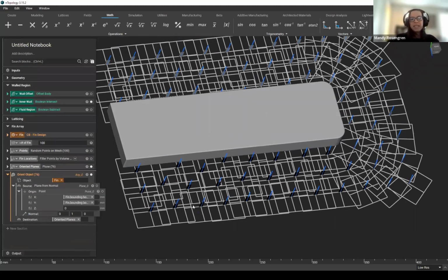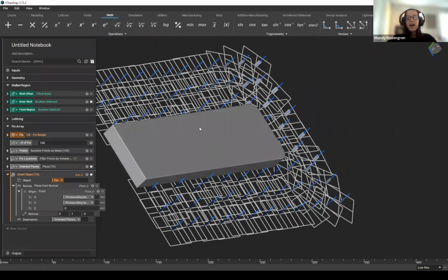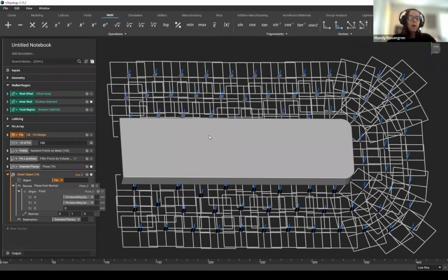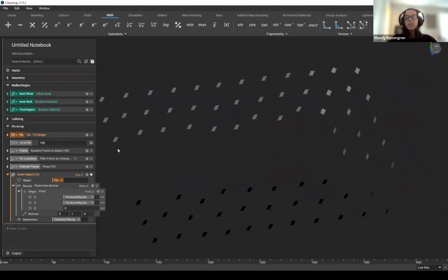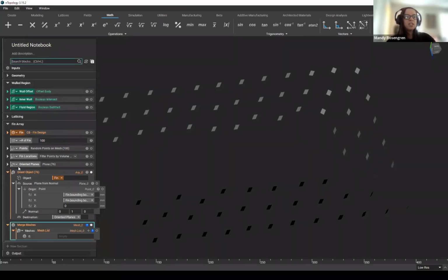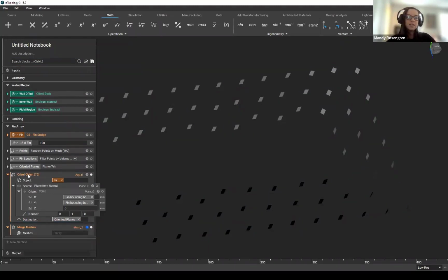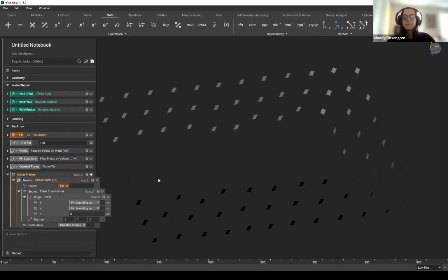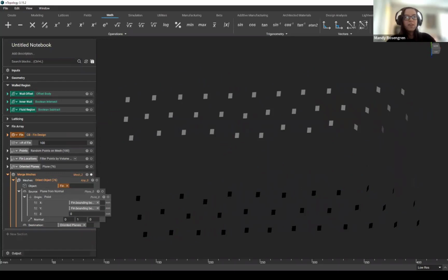So that's our orient object, and using that evaluate field gradient definitely can be a few extra steps than that closest point. So you might just want to use that option as well. But now that I have this orient object, so I'll type I so we just see these fins, I'm going to merge them all together. So I'll do a merge meshes. And since this is already a list, I'll delete our mesh list and place in this orient object. So now I have one item out of all of these.